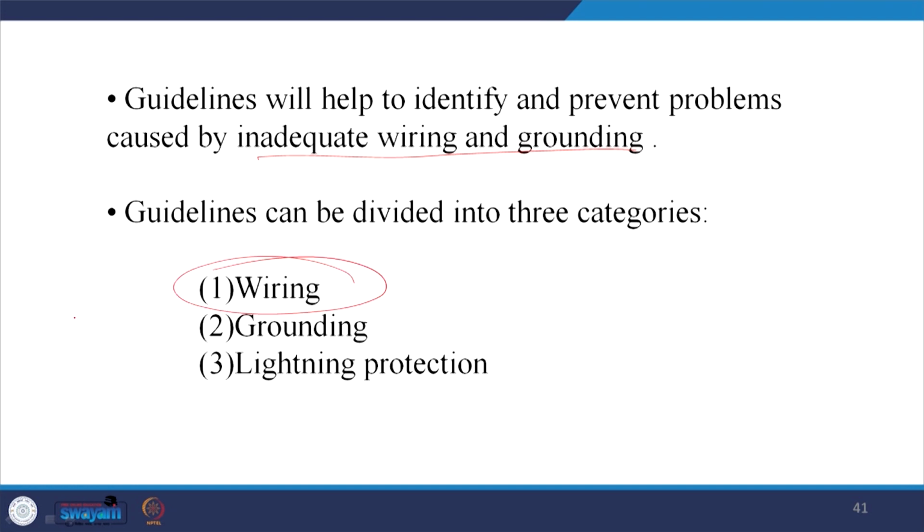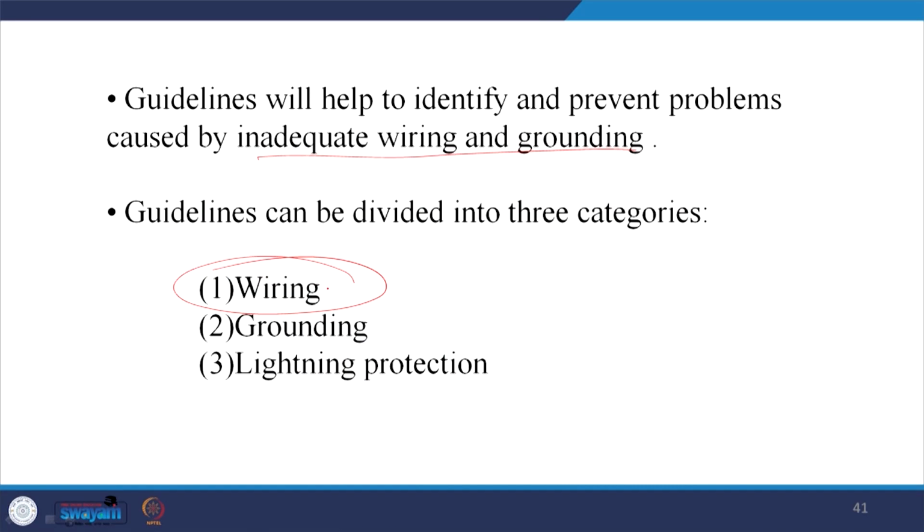One is wiring. You should ensure that loads are distributed across all the phases of the house in the right manner, so that you do not inflict a huge amount of unbalance into the system. Moreover, if some portion of it has adjustable speed drives, then try to contain the adjustable speed drive harmonics and give a sink path, so that they do not propagate to the whole area of this power network.